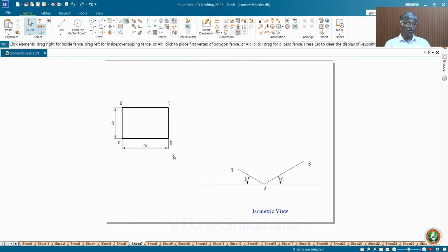Now, as I told you earlier, how to draw the isometric projection of the square, rectangle and circle. For all practical purposes, I draw the isometric view. So assume that you are drawing the projection, I am keeping the view because it is easy for me to explain with the actual. Otherwise, you have to reduce it and do it. You can do it at home. So, practice it. Now, as I told, here I am looking at this in this direction. The nearest point is A for me. On a horizontal line, you fix A, and then to the left of A, draw 40 mm, and then to the right it is 60.